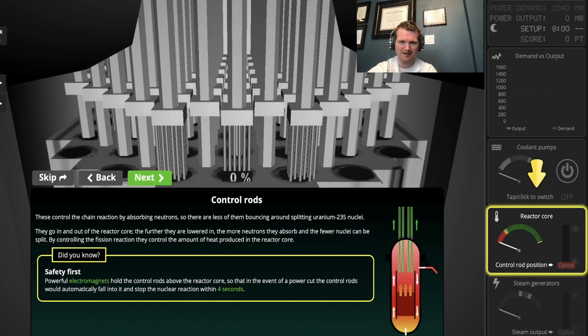Now, one thing to keep in mind, they're not showing units here for simplicity. The far left isn't 0, and the far right isn't the maximum temperature it can possibly withstand. The far left is probably on the order of 560 degrees Fahrenheit, and the far right is on the order of 630 degrees Fahrenheit. So it's a pretty short range. And considering the amount of water that's in there and the amount of temperature and pressure, 1 degree has a lot of impact on thermal expansion. Pressure is on the order of 2235 psi, by the way.